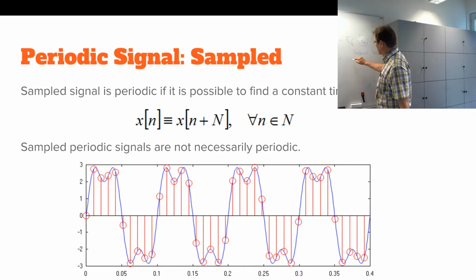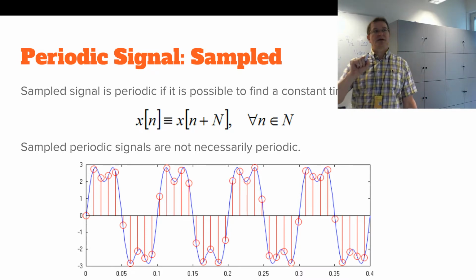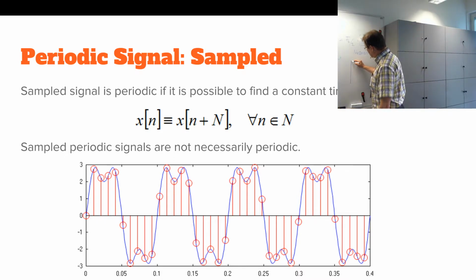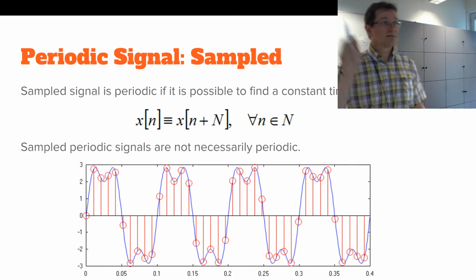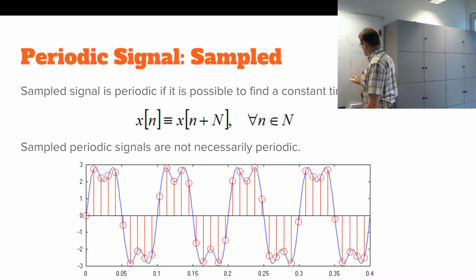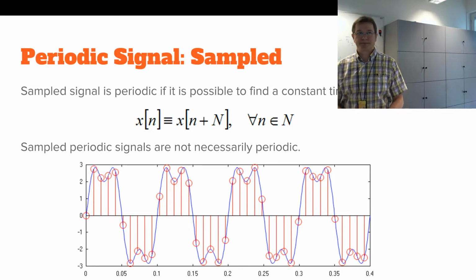For a sinusoid, you get just one single peak. But when you sample it, you will always get an envelope of other frequencies around it. Always. You get side lobes.